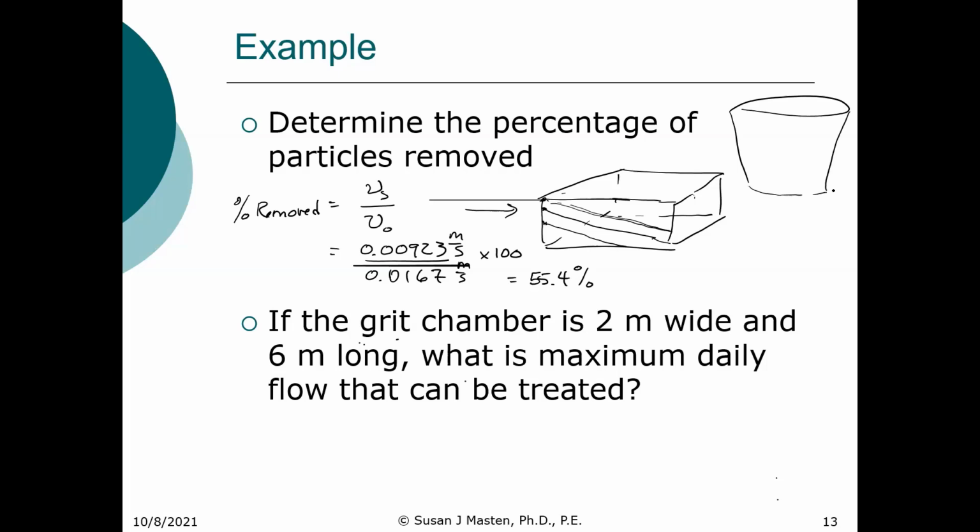So if this were an upflow sedimentation basin, it's not a great diagram, but basically the water flows in a center mixing, flocculates in this interior cone on the inside, then flows up through this sludge blanket here, and then out over the weir on the top. So the liquid flow is up, and the particles are moving down.